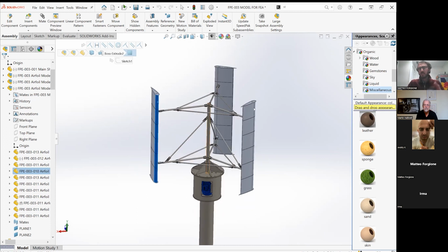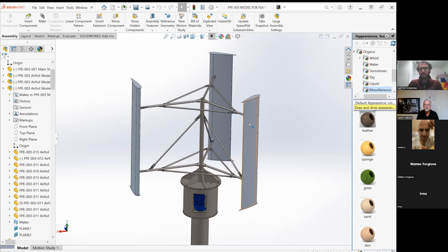So this is simple to manufacture. It can be made with a standard NACA airfoil design, which you know all the characteristics of. It can be fabricated out of aluminum and welded, and then we have a steel frame, hollow steel shaft, and then the main motor housing, which the motor in this case is acting as a generator.